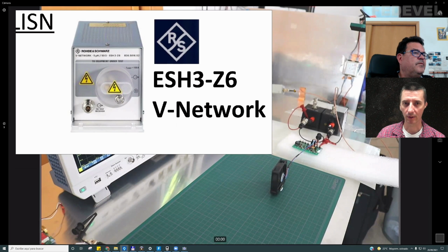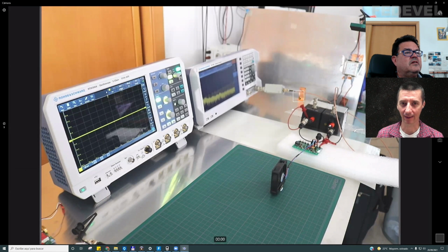I guess everyone noticed all these metal tapes. So does it mean we need to very well connect all these boxes to the ground? Yes, exactly. I am trying to fix all of them, not specifically in this case, because this is a metal box, but it's painted. The problem with the paint is that it's not conductive.